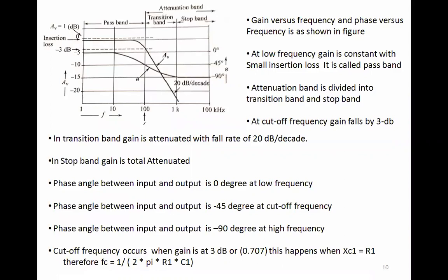Now this is going to be the graph for the first order filter. So as I was mentioning, it has a 20 dB fall, right? So this is our low pass filter, because this is a pass band region, and then it gets into a transition band and then stop band. Why is it transition? Because it's moving from a high value to a low value, right? So since it's moving from a higher value to a lower value, we term it as transition band. And then it is in stop mode because there is nothing there, right? So stop band, transition band, pass band. Okay.